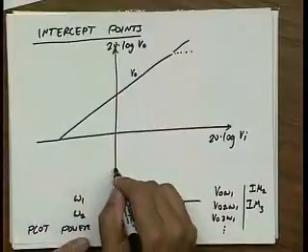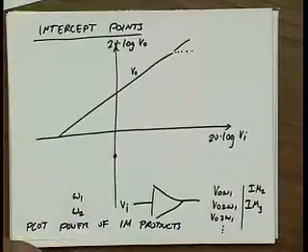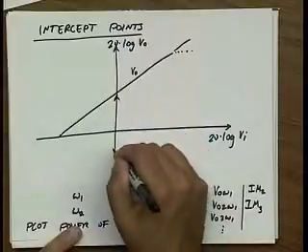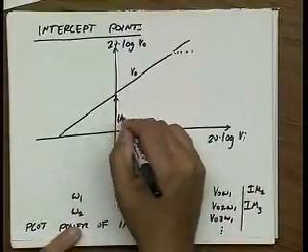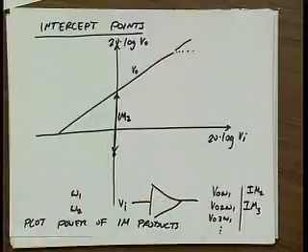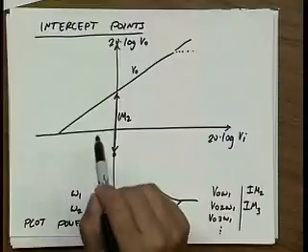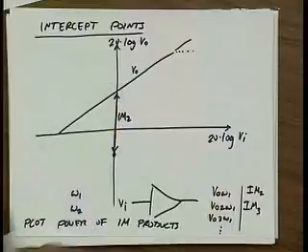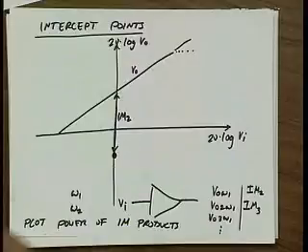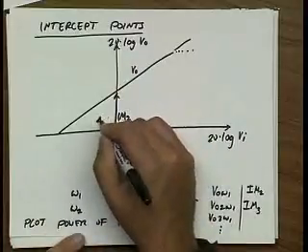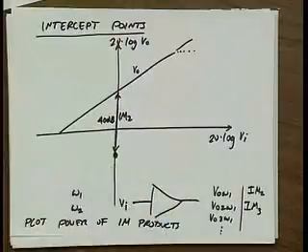In particular, let me look at the power. Let's say I go out here and I measure that at a certain input power, my IM2 is down by this much. So IM2 is a ratio between the intermod component and the fundamental component. On a log scale, it's just this difference. Let's say, arbitrarily, this is 40 dB. That at a certain input power level, my intermod power is 40 dB down from the fundamental. Well, how does it vary with input? If I vary my input, what happens to this intermodulation component?